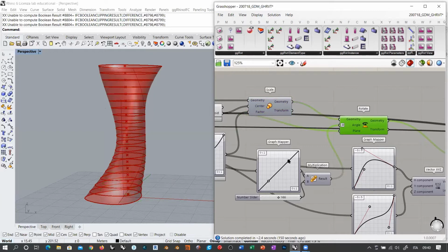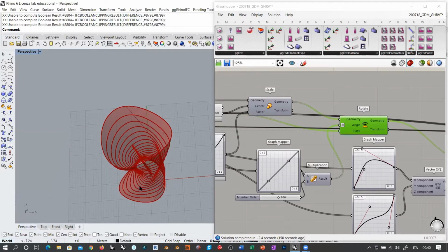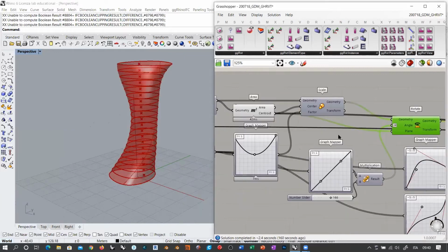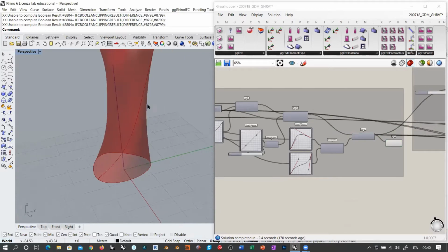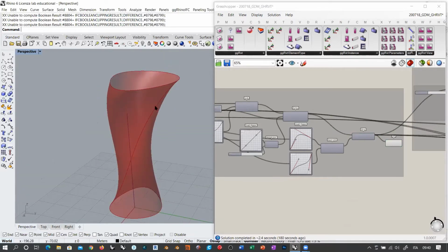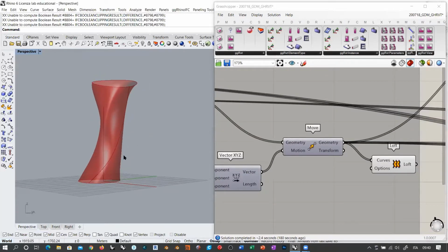Then there is a linear rotation. In this moment, you see that the rotation is linear. So basically, there is some twisting occurring. It's not so visible because of the organic shape. But you can see that there is some rotation here. And actually, you can also recognize this if you look at the actual surface. You will see eventually this seam here that flows all along the vertical loft. This is actually a loft surface. And so this is actually the only thing that is telling us that this is a twisted surface, okay?